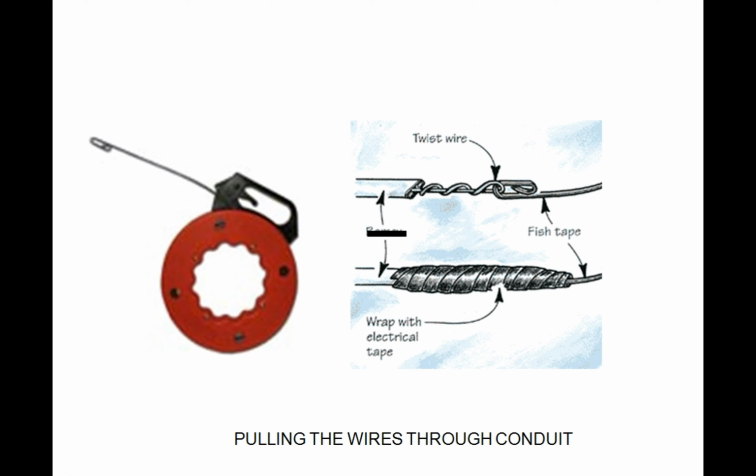Mousing it is by tying, from one side of your conduit, a rubber bag to the wire that you're pulling through, the conductor wire, say a number 12 or a number 14 type. And then on the other side of that conduit, you connect a vacuum or a hose, and then you use suction on that bag to pull the wire through. Once that bag that's carrying the wire gets sucked into the other side, then you've made your run, and you can tie off your conductor to wherever it needs to be.